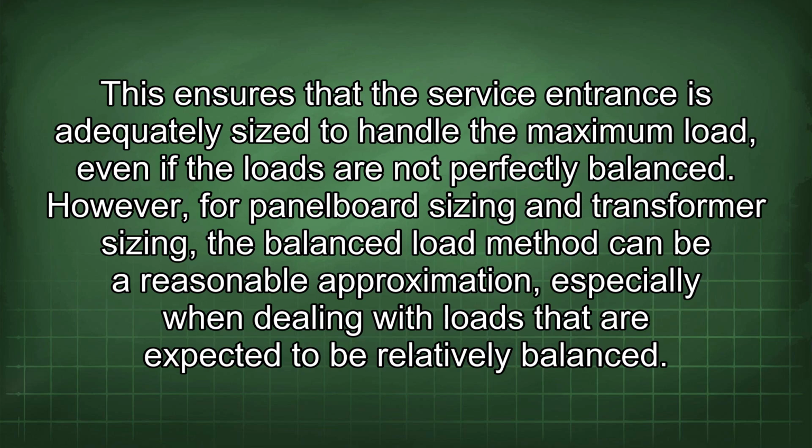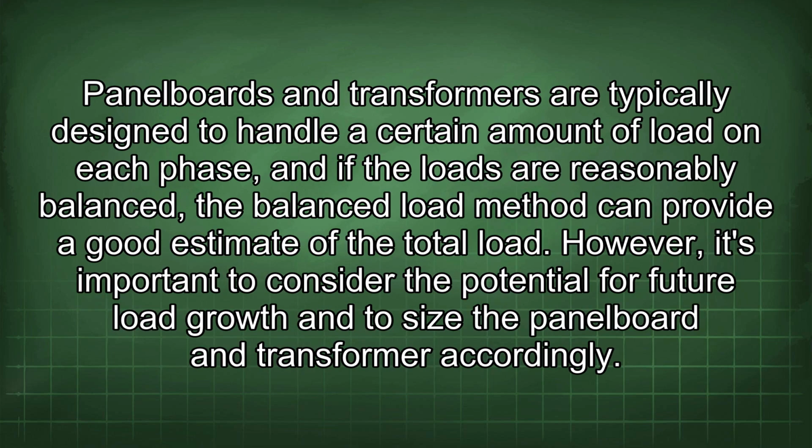perfectly balanced. However, for panel board sizing and transformer sizing, the balanced load method can be a reasonable approximation, especially when dealing with loads that are expected to be relatively balanced. Panel boards and transformers are typically designed to handle a certain amount of load on each phase, and if the loads are reasonably balanced, the balanced load method can provide a good estimate of the total load. However, it's important to consider the potential for future load growth and to size the panel board and transformer accordingly.